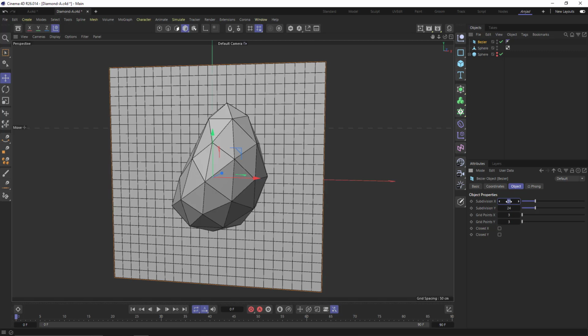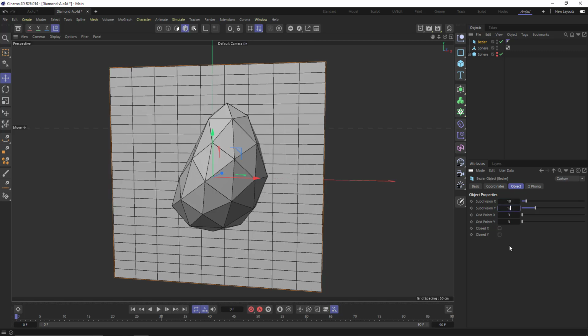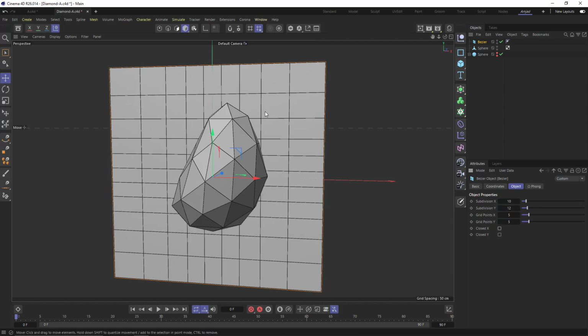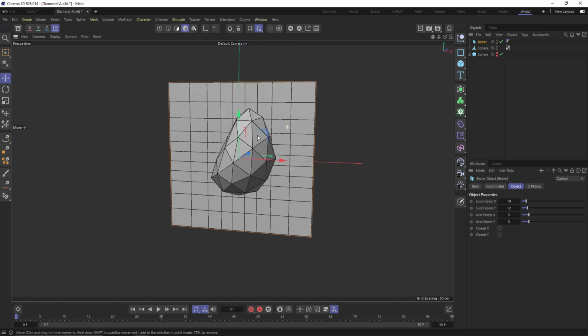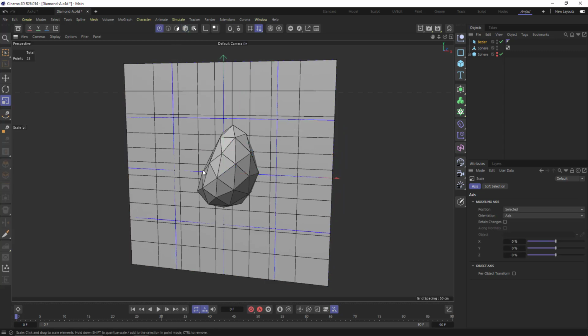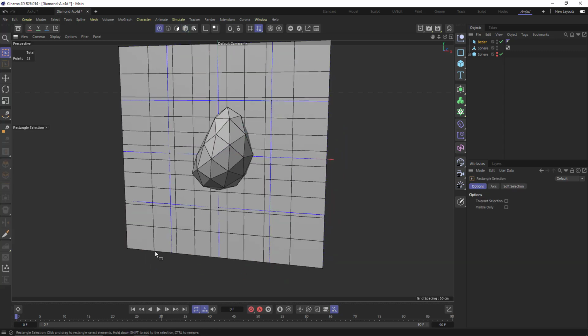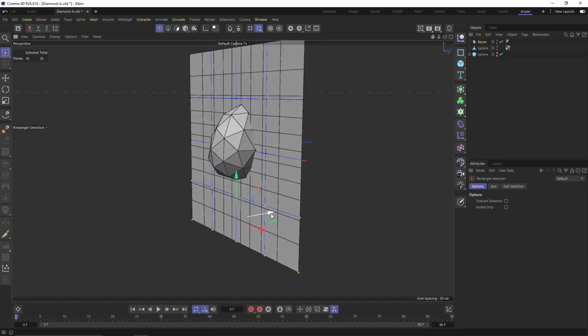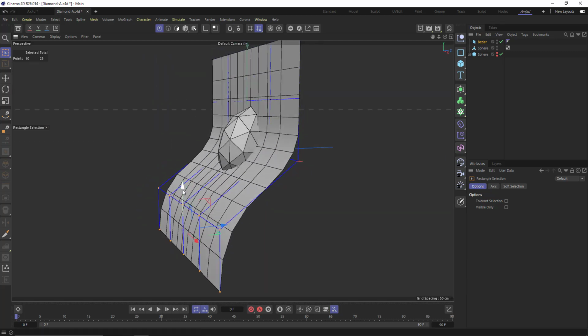Create an L-shaped background for later rendering with rounded corners using Bezier. There are many ways to create a floor like this, you can use any of them, but I found this method easy for you to control whenever you want.